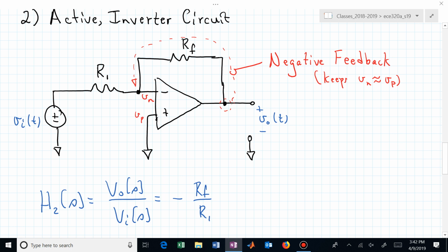And what does this transfer function tell us? It's an inverter, isn't it? It's negating what we put in at the input. This now tells us if we put in something at the input voltage side, we flip the sign, and is there any memory or is there any transient behavior in this particular circuit? If I wiggle the input, when will I see something wiggling at the output? Instantly, right? This is just a scale change. This is just an inverter.